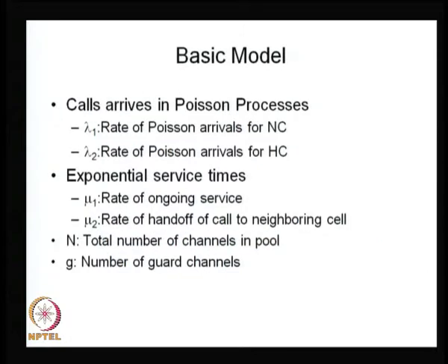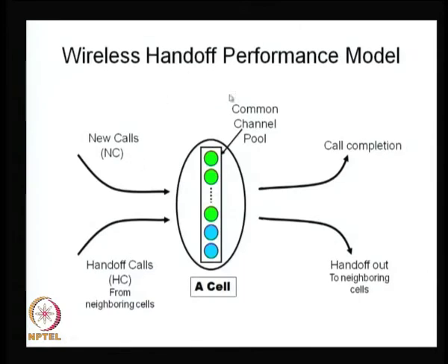That means out of capital N channels, you reserve a few channels for the handoff calls, not physically few channels. Whenever you have a few channels left in the system, in the pool, if that number is more than the reservation, then you keep allowing the new calls as well as handoff calls.